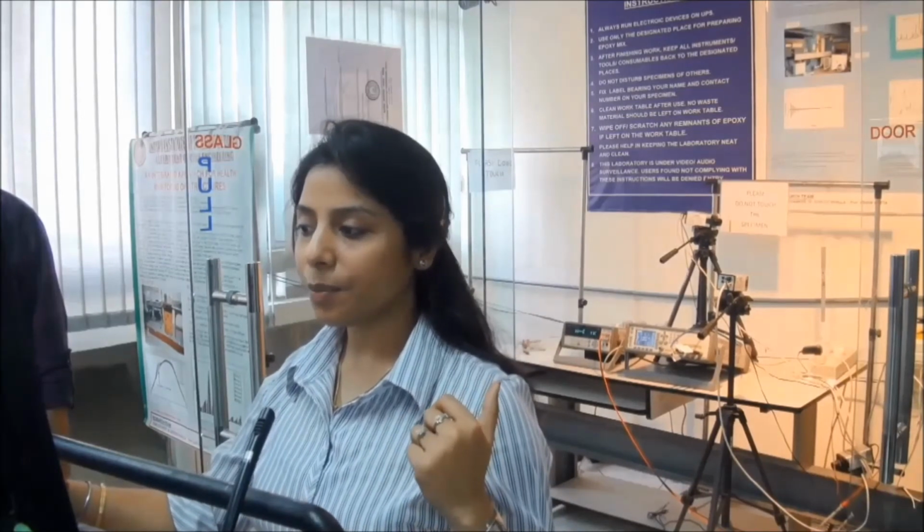First I want to know, can anybody tell me why I'm getting two peaks here? I've watched the whole setup of experiment number 1 carefully. You would have seen that the hammer which is hitting the beam is hitting the beam at constant intervals of time. So as you chose 10 seconds, 10,000 readings at 1 millisecond interval, in that 10 seconds it is a possibility that the hammer has hit the beam twice. So you got 2 peaks actually. It's not 2 degrees of freedom.